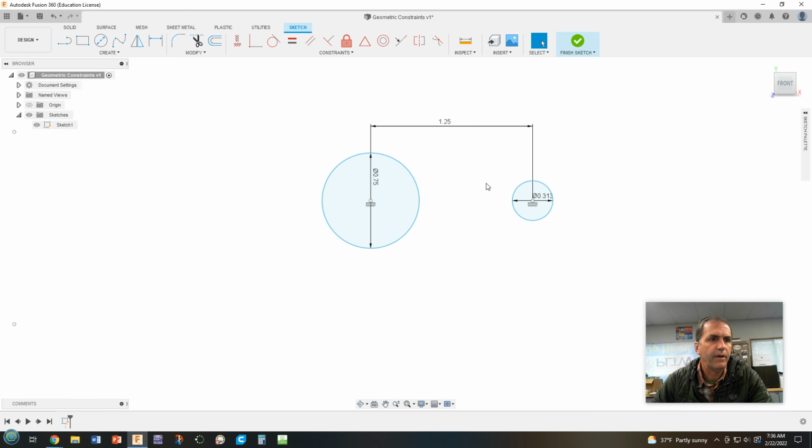All right. So now we need to make some lines. We're making kind of a little crank thing with lines going from one point to the other. Watch carefully. We're going to have to use coincident. Coincident happens a lot when we're connecting two things together. In fact, let's show you how that works by making our line a little bit off. So a little to the right of the center point there, we're going to go here, and make another one just to the left of the center point over there. So you've got a line that looks like this.